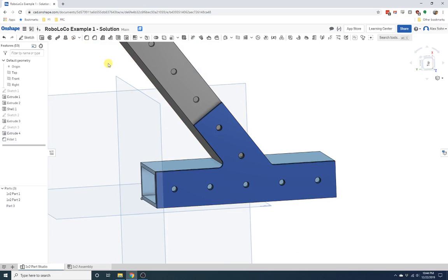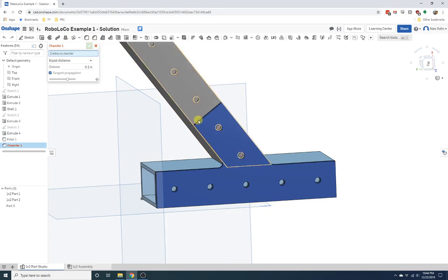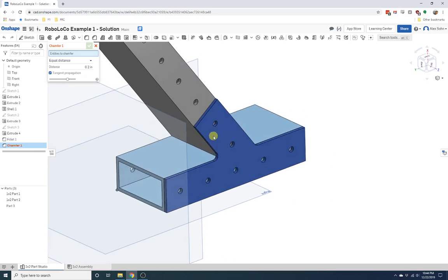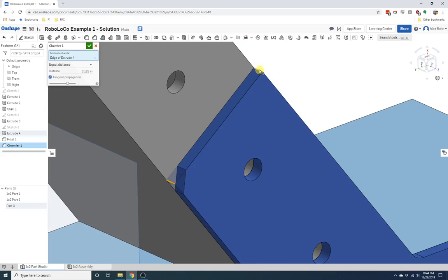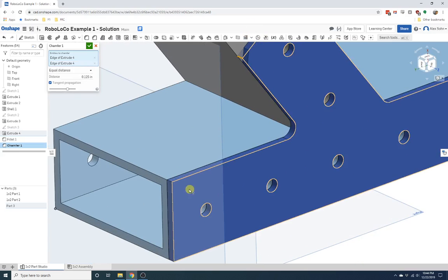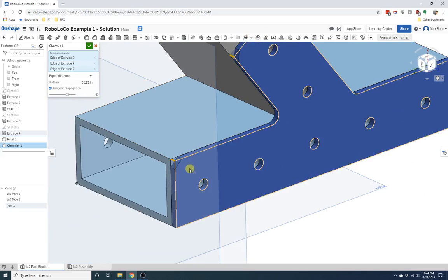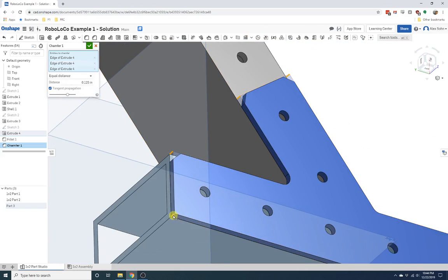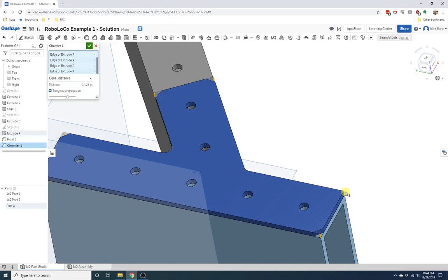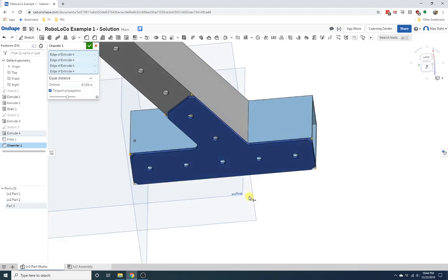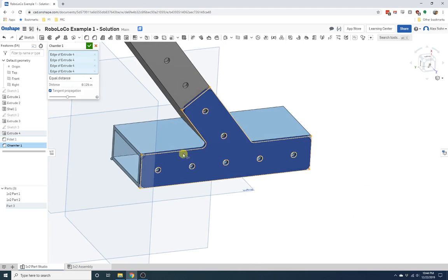So as you know, when we do inspections for the robot, they always look for sharp corners. So one thing we can do to get around that is chamfering these corners, basically just cutting off the corners. All right, so we're going to do that. Okay, there is our bracket.